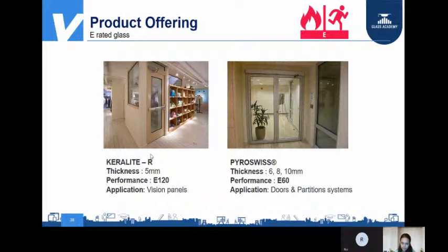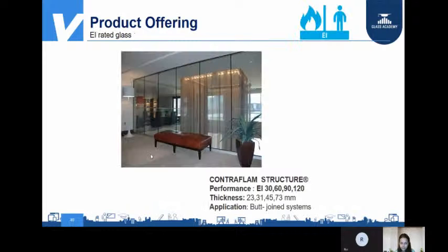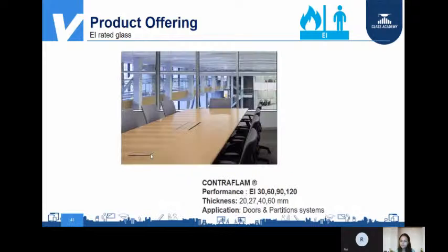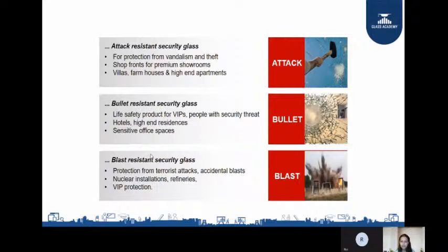Okay. So now we have different types of glass when it comes to innovation also. The first is SAGE or dynamic glass. What happens here? You can actually control the tint and the solar factor of the glass. It can be changed according to your wish. You can do it with the app, the remote, or the switch, or you can connect it with the BMS system of the building, and according to the sun movement, it will change the VLT and solar factor of the glass. We can call it dynamic glass also.